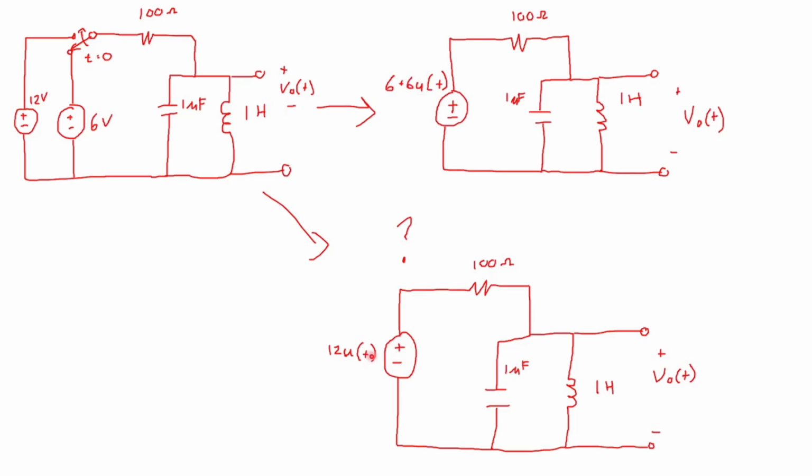We are allowed to use the single-sided Laplace transform because what we are going to do is be in a situation where all of the information about past values of t is all going to get wrapped up in the initial conditions. So we use the single-sided Laplace transform in combination with the initial conditions to cover all of time. Now, if it matters to us what is happening, or if things aren't so simple for time t less than 0, then we might have to be a little bit more careful.